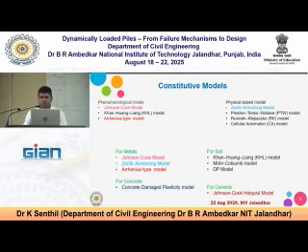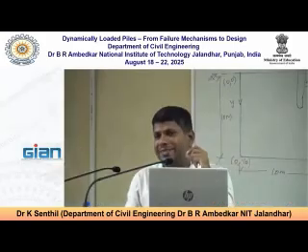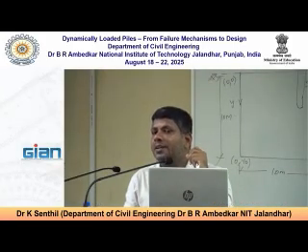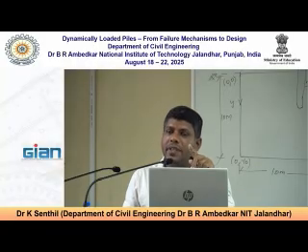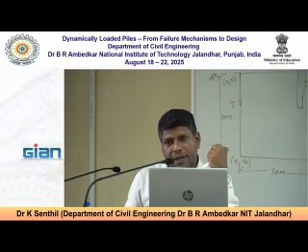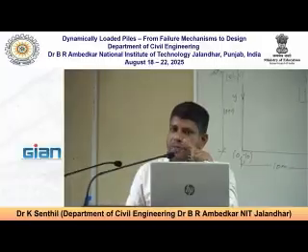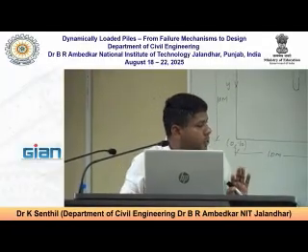Okay, for soil you can use a Mohr-Coulomb model and a Drucker-Prager model. These are familiar models, so you have to characterize those parameters very precisely. Now if you look at this DP model, the Drucker-Prager model, yes, there is a constitutive model. It's inbuilt already for porous material. It is available. Now let's go to Abaqus.